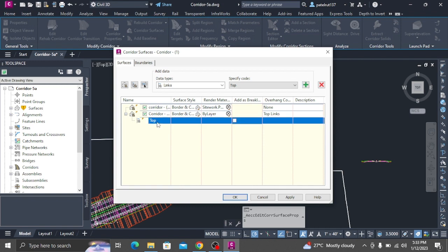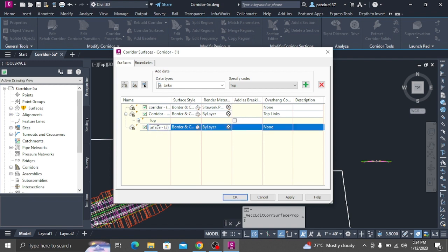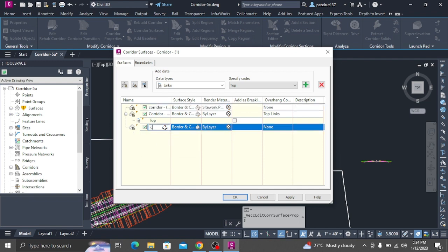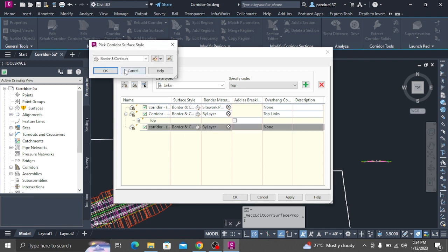Outside Boundary: used to define the outer boundary of the corridor surface. Hide Boundary: used as a mask to create void areas or punch holes in the corridor surface. For example, a corridor might use a link code Paved on either side of the corridor with another surface, a median, separating them. When you create a corridor surface using Paved as the data, Autodesk Civil 3D tries to connect the gap in between the two link codes. To create voids, you define boundaries to represent the surface appropriately.